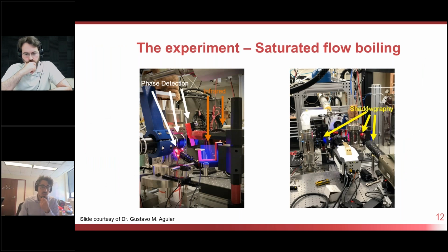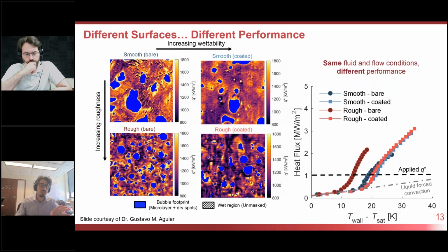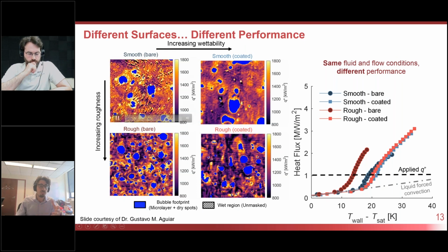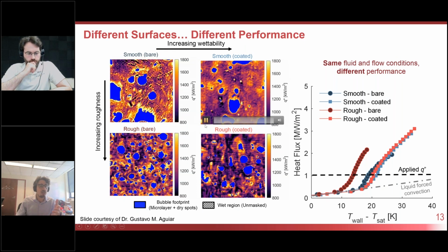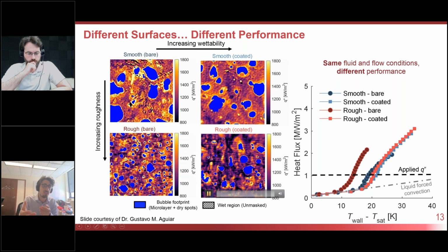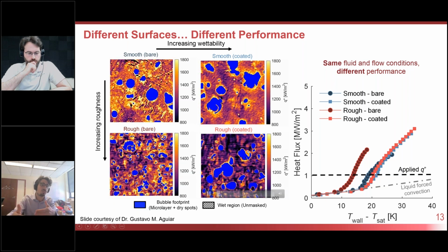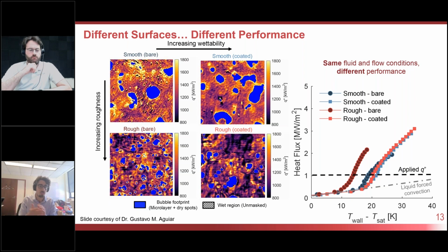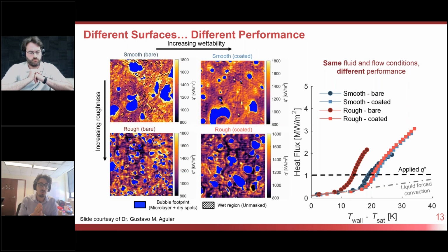This is done in water, and what he did is a very similar analysis, but in this case it's for water on rough and smooth surfaces, to see the differences between the heat transfer mechanisms at the surface. And here you're already seeing the result of the inverse conduction problem that I was talking about before.